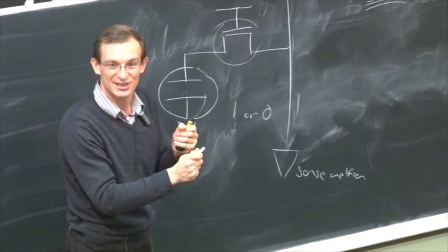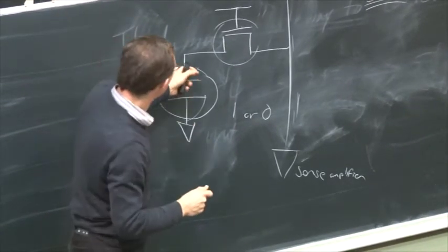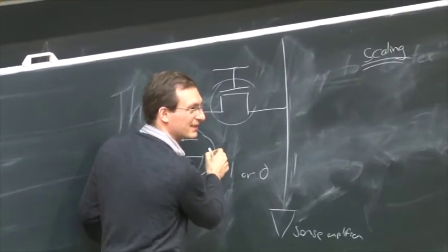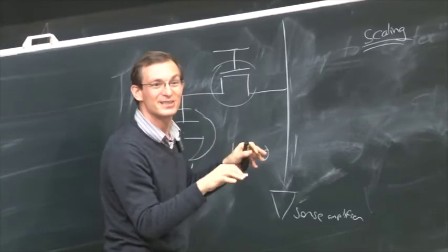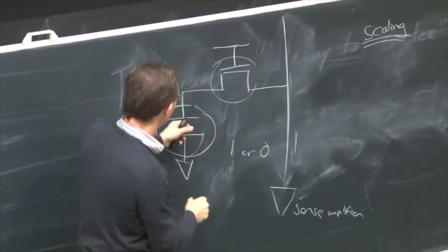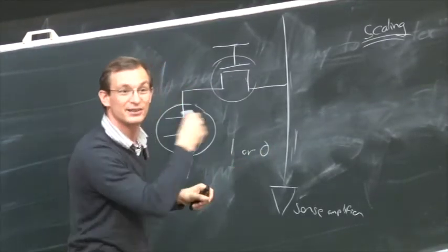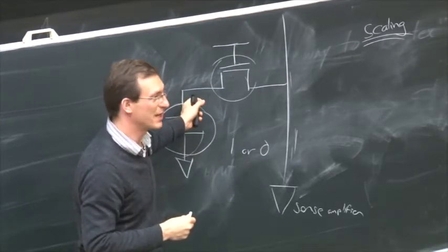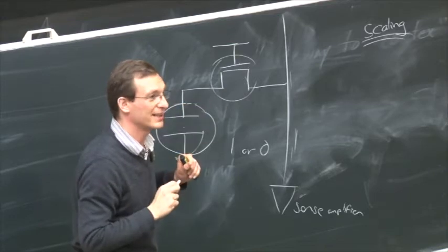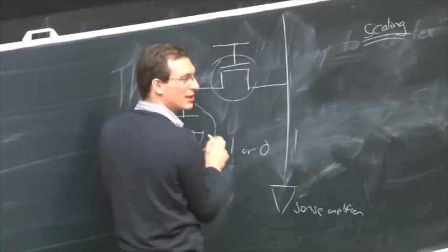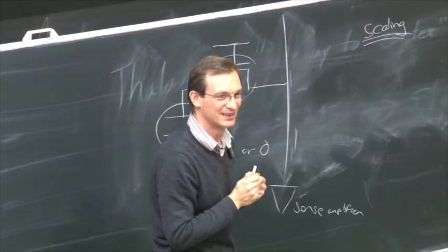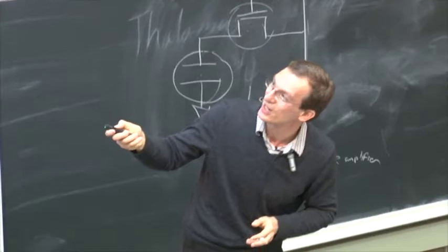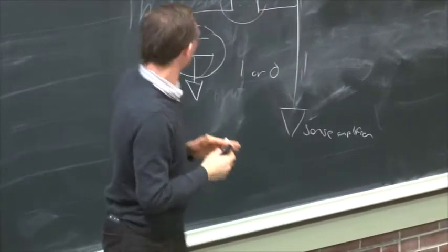It leaks the charge. Now, once it leaks the charge, you need to refresh this capacitor more often, right? You've studied DRAM earlier. You know that this charge leaks, so you need to periodically refresh this capacitor to be able to store data reliably. Now, once you make both of these smaller, the charge leaks much, much faster. So you need to refresh more often, which means that you need to consume even more energy.